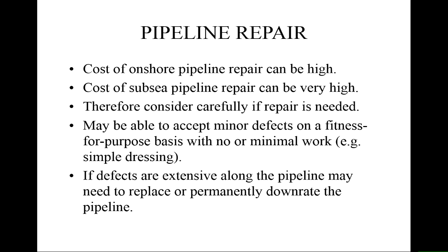It is good because here we have sharp corners which act as stress raisers, while after grinding you create a more rounded shape of that defect, so it won't pose a problem. Obviously, with grinding, there is another problem. Do not do that extensively, because it will raise the temperature in the pipe, and it might induce phase changes.